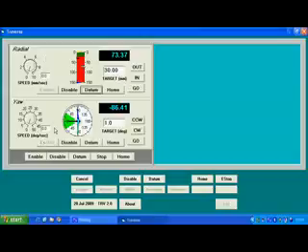We can enable it, datum. Again, the datuming is on the anti-clockwise limit switch. It appears to be going negative at the moment, but once it touches its limit switch, it will datum itself. There we go. Although we're up against the anti-clockwise limit switch, the position has been set to -86.4 degrees, and again this offset is read from the initialization file.